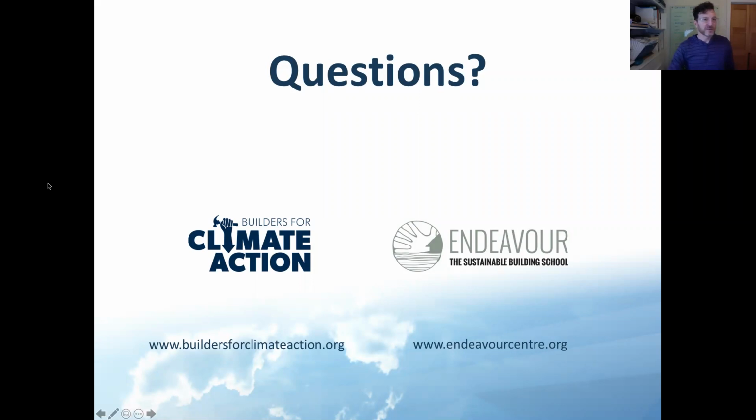Duncan Patterson, rule of thumb, what are the biggest things we can do as builders to reduce embodied carbon? Use less concrete and use high SCM concrete. Concrete tends to have the biggest impact, especially at the residential scale where the basement is a fair amount of the volume of the material, and it's hard to use non-cement based materials down there. So, the more you can bring a building above grade and the less concrete you can use and the lower the carbon footprint of the concrete, the better.